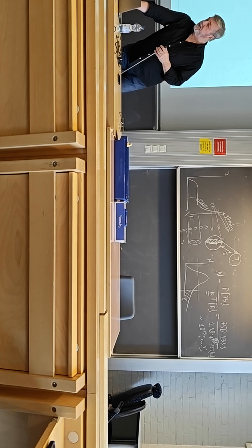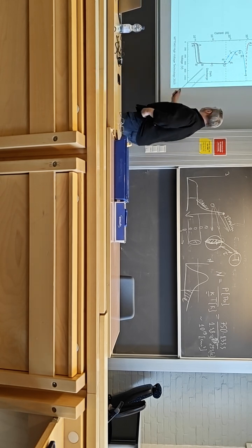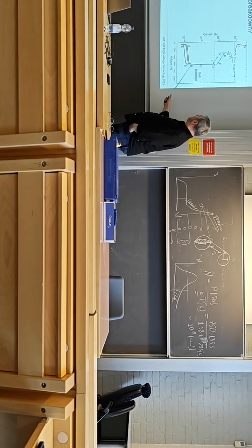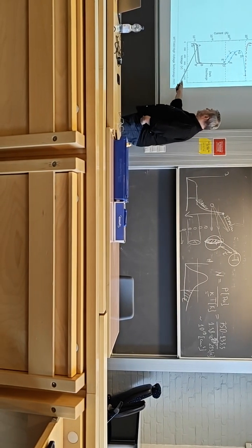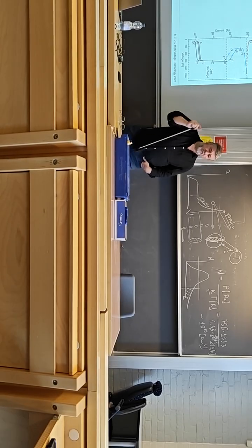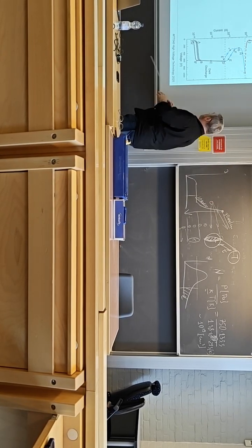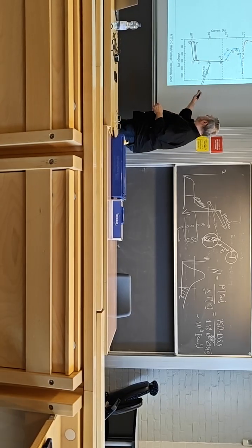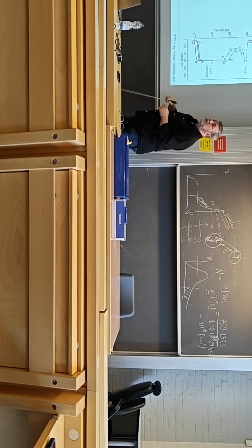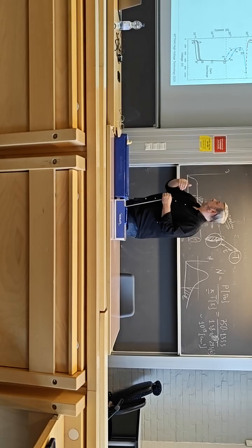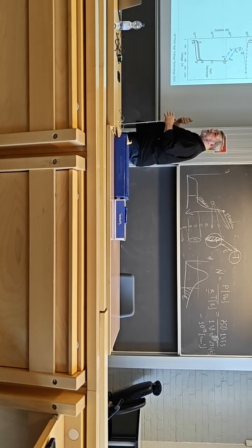Now we come to the point: what is electrical breakdown? We know now what happened here. We have some particles which are created by external factors. Then by applying the electric field, we have this region where particles can be multiplied because of impact ionization.